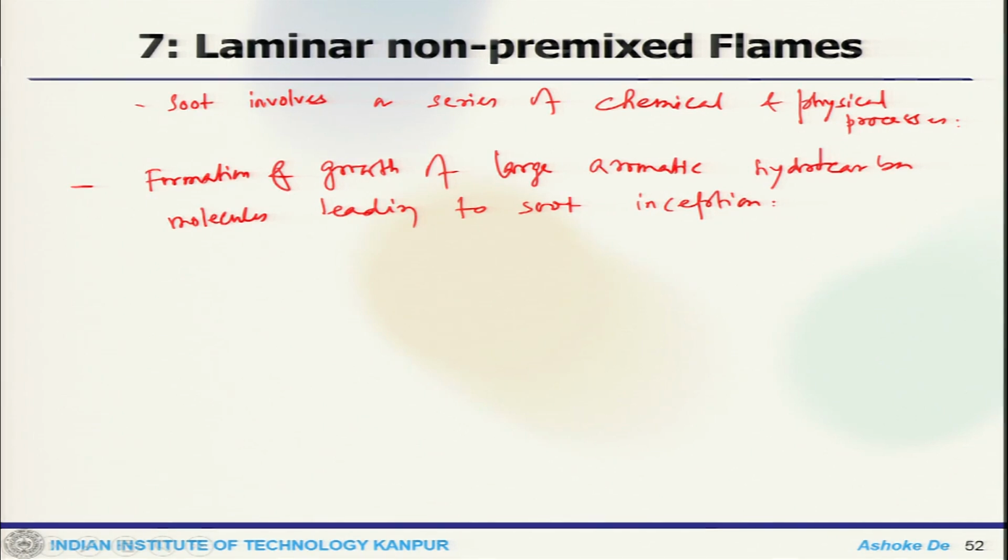That is probably the first step towards soot formation, where large aromatic hydrocarbon molecules form and grow. This is called soot inception. That means this is the transition to the first solid particle.